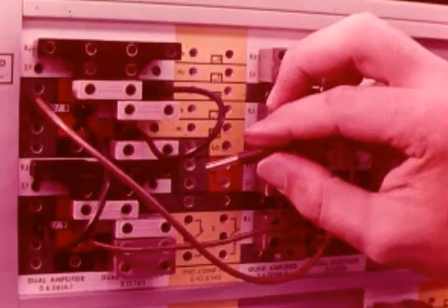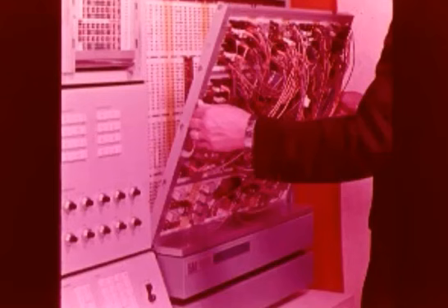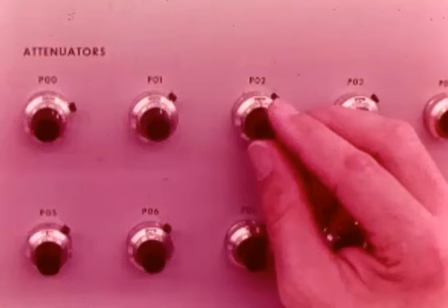The actual programming of the computer is simple. Using the diagram derived from the system equation, interconnect the components at the computer program panel. Place the program panel on the computer. The program panel, it should be noted, is removable. Programming it off the computer does not consume valuable machine time and allows other problems to be run in the meantime. After a problem has been run, the program panel may be stored for future use. Next, set the potentiometers to the system parameter values, and the problem is ready to be checked and run.